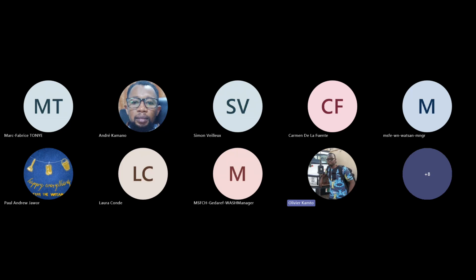In whatever situation, if you have drilling to do, you have your Watsan focal points for your missions. Please try to associate them as early as possible and discuss with them, so that we follow the procedures as much as possible. Recently, in one of our projects, a borehole was drilled, and before we could even run the pump test, the borehole had collapsed. That was in less than 1 week. The pump could not get into this borehole. So the specifications which we give are very important and vital that we should try to respect.